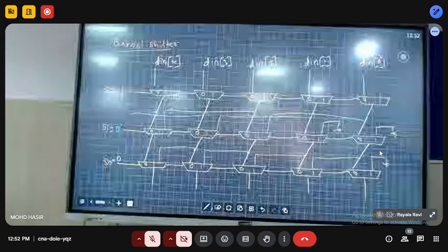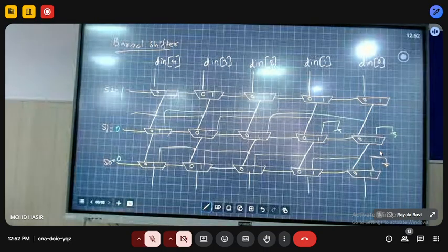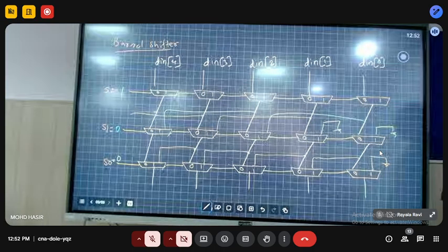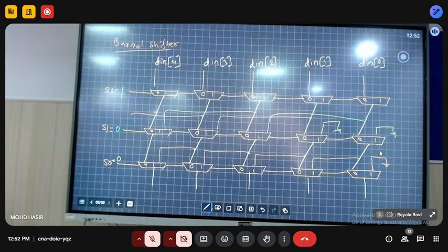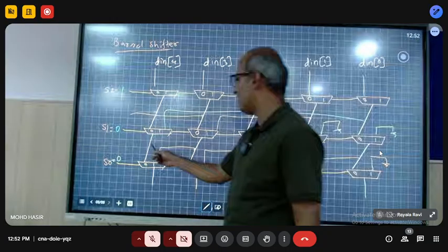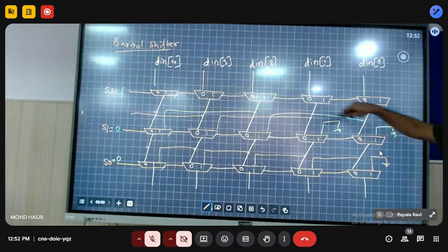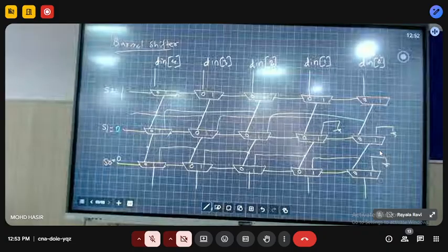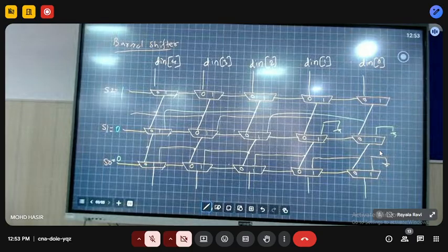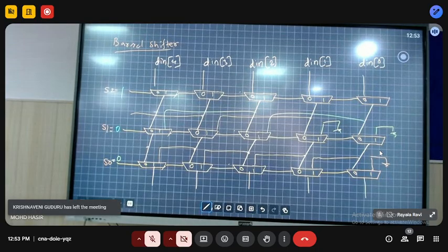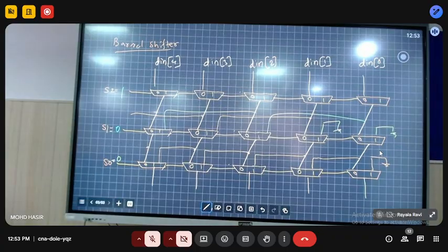Right. So that is what a barrel shifter is. A barrel shifter is nothing but a huge chain of multiplexers. DSP chips, TI chips use this concept of multiplication. Okay. Now we can add complications. Every single simple step I will add complication. So what is that? If I can do this as a rotate, shifting left is multiply by 2 to the power n. If I change the direction, divide by 2 to the power n. So you can have one more stage inserted in between, and you can decide either to multiply by 2 or divide by 2, multiply by 4 or divide by 4.